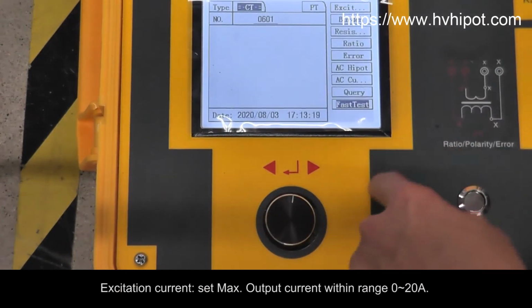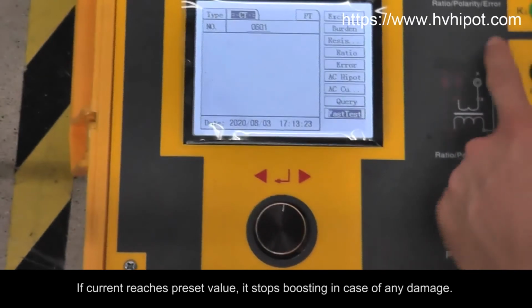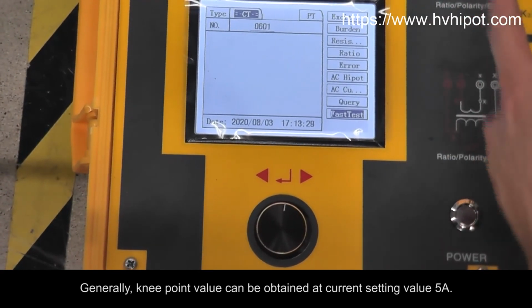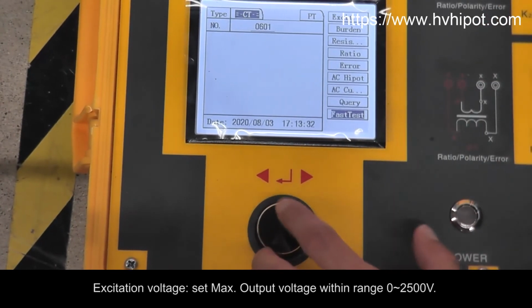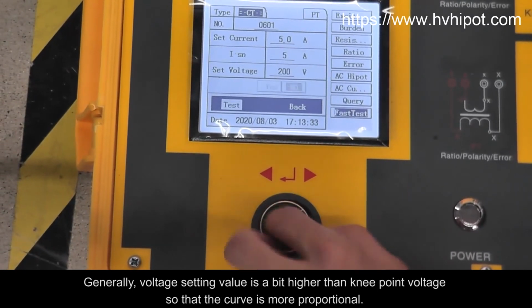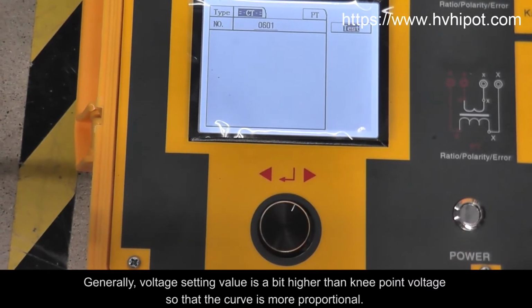Excitation current, set max. output current within range 0 to 20 A. If current reaches preset value, it stops boosting in case of any damage. Generally, knee point value can be obtained at current setting value 5 amperes. Excitation voltage, set max. output voltage within range 0 to 2500 volts. Generally, voltage setting value is a bit higher than knee point voltage so that the curve is more proportional.